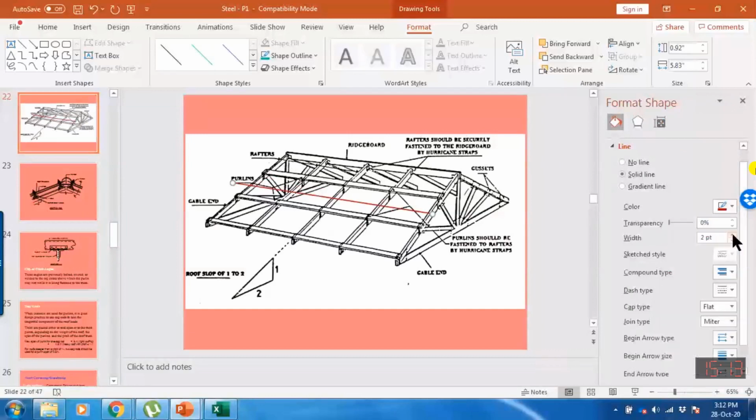Here, between this purlin and this purlin, we have to use gravity load. In gravity load, we have to take the horizontal distance between these two top joints, which is called the panel length.